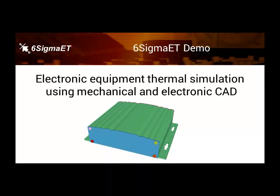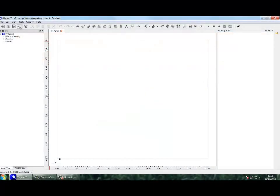In this video, I'll show you how to create a thermal model of an item of electronic equipment using mechanical and electronic CAD data in 6SigmaET. The thermal simulation will be used to validate and improve the thermal design of the equipment. First, we'll import a 3D CAD model of the enclosure.